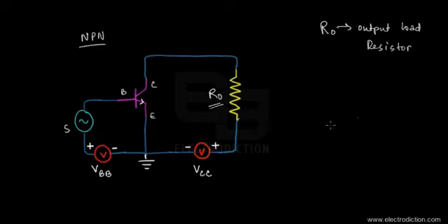While we're using the BJT as an amplifier, it's natural that we shall use it to amplify physical quantities like sound, speech, music, whatever. All these quantities are AC in nature, so we're using an AC source because we want to see how a BJT could amplify any AC voltage signal.